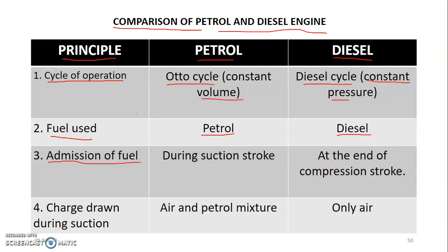Next, admission of fuel, or entry of fuel into the engine cylinder. During the suction stroke, in the case of a petrol engine, the mixture of air and fuel will enter the engine cylinder. We know that already, we discussed it. And here, at the end of the compression stroke, only the diesel will be sprayed by the fuel injector in the case of a diesel engine.